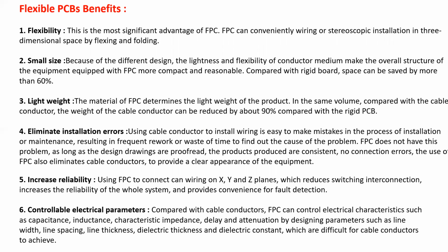Then the next one is eliminating installation errors. Installation errors are minimized, and there is no wastage of material or wastage of time to find the fault. The next point is increased reliability. Using these boards, we can connect the wiring on X, Y, Z planes, that is, 3-dimensional connections are possible. The next advantage is controllable electrical parameters. Using this, we can control the capacitance, inductance, characteristic impedance, delay and attenuation by designing the parameters of line width, line spacing, and line thickness.